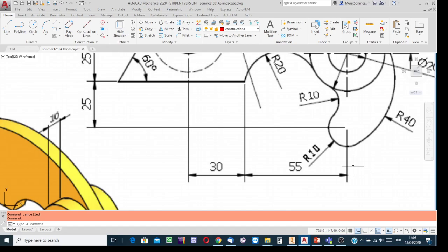Since at the creation stage for such circle arcs cannot know where are the tangent points, you know, the only thing to do is that imagine the circle arc as if it were a full circle created, and after creating the other tangent entities, then applying trimming, delete the rest.